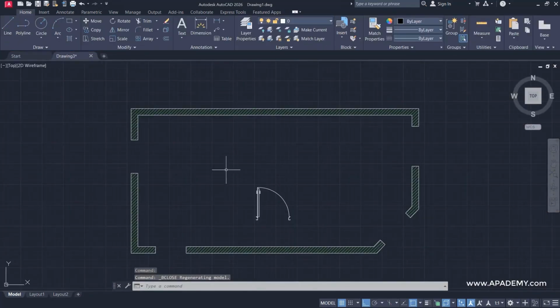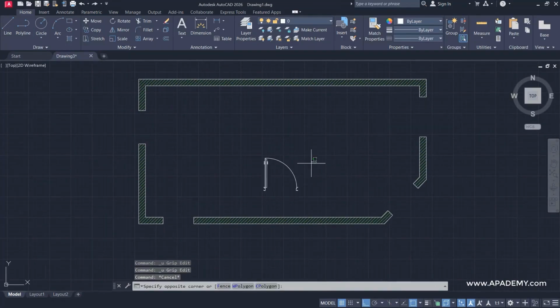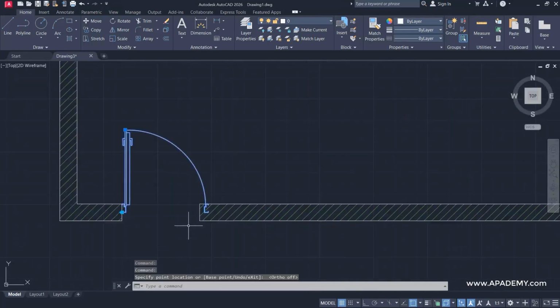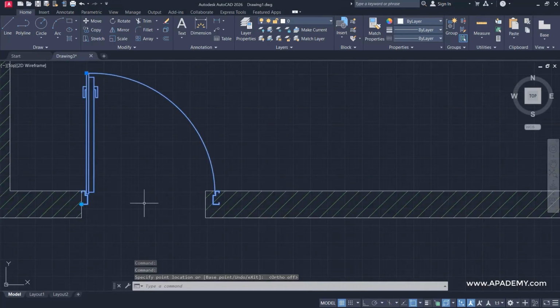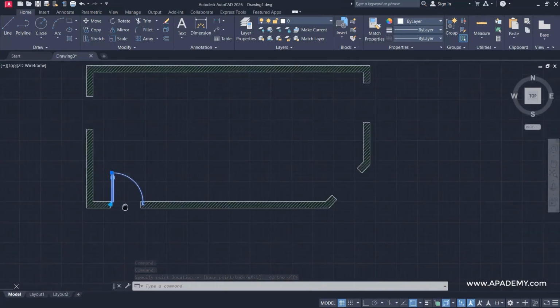I'll save this and go into my workspace. Now I can select this object or block, which is now smart, from the same point that's the alignment point, not the base point up here. I can grab it from the alignment and place it wherever I want. I'll turn off F8. For example, I'll say be here. OK. I still haven't adjusted its dimensions and size.